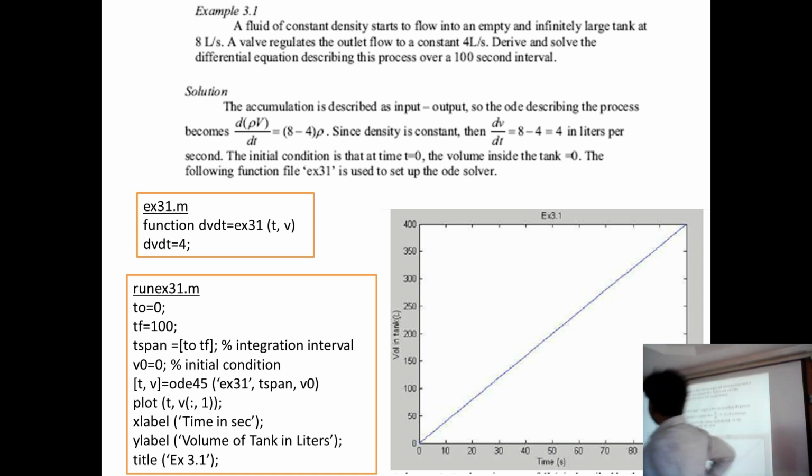See, what I did is you look at solving with ODE45. Always when you want to solve differential equations, you have to open two M files. One M file for the function, another M file for the ODE. So this file is for the definition of the function. What is the definition of the function? What is given, you have to represent that. Function, output variable, file name or function name, and what are the independent and dependent variables. Write the expression of the differential equation. Close it. Open one more separate M file. Define your ODE45.